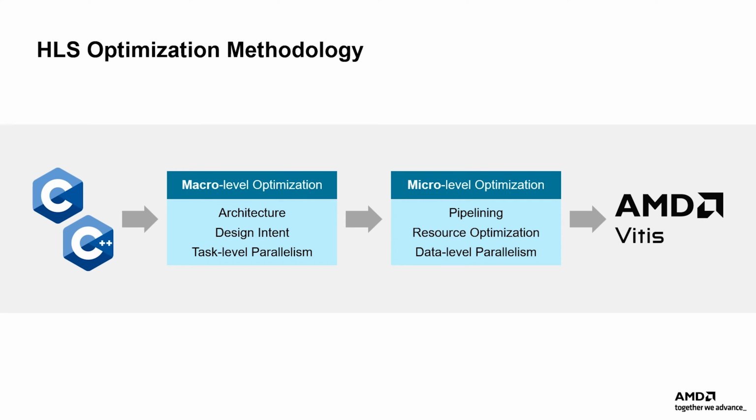To allow for optimal performance and area utilization in your hardware designs, Vitis HLS offers a variety of optimization pragmas, such as pipeline, unroll, and array partition. By strategically applying these pragmas, you can fine-tune your microarchitecture to meet specific goals. By combining these optimization techniques, Vitis HLS enables developers to create efficient and high-performance hardware implementations from their software designs.